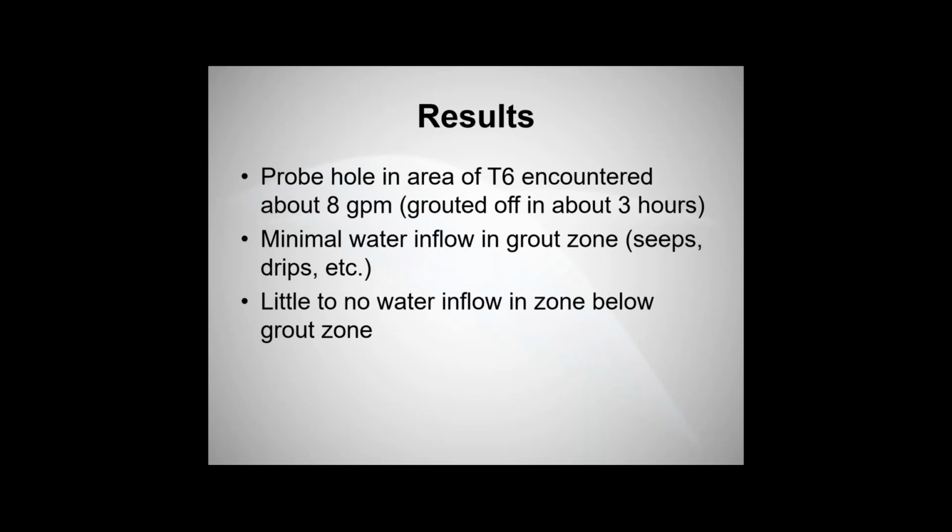Other than that, there was obviously minimal water inflow. There always is. As Adam mentioned, grouting does not get you dry. Grouting gets you minimal water inflow that you can handle with reasonable means. And then essentially below that 100, and somewhere between 150 to 180 foot, there was little to no water inflow, which essentially just confirmed the water test data.